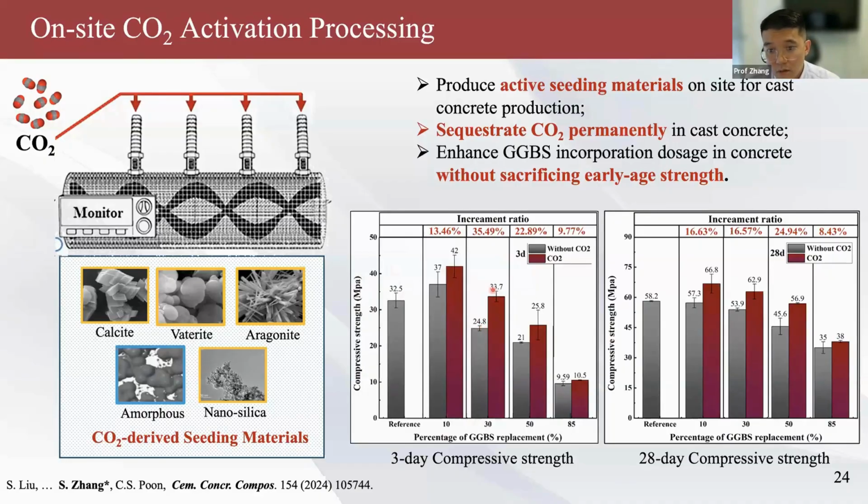And this is a 3-day compressive strength. At 28 days, we see the same trend. For example, at a 50% replacement ratio, a similar level of strength can be achieved using the CO2-derived seeding material, the CO2-derived activator.